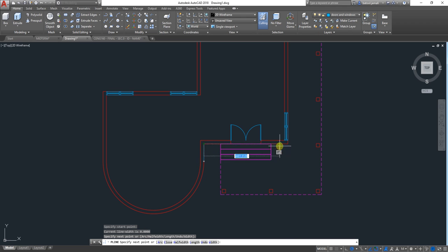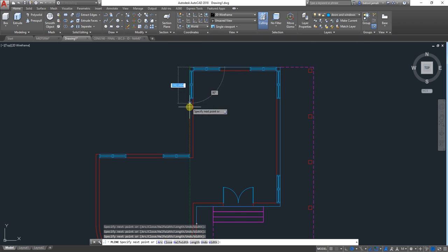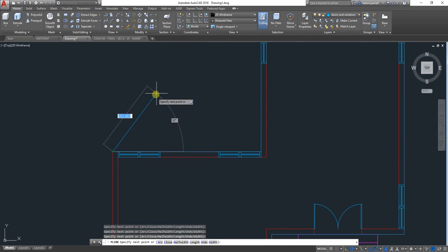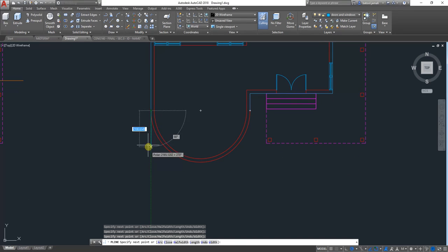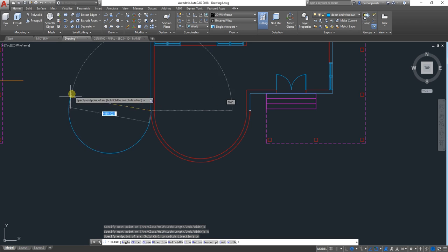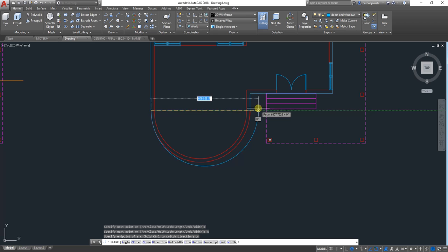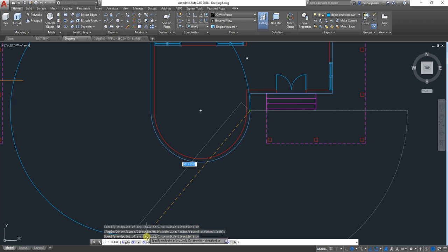Go around all the outer corners of your plan, just from outside. You don't need to go inside because we need only the borders. So this point, and then when we come to this part, we have an arch here. For this curve or this arch, you need to go down to the command panel and select arc here. When I select arc, it will give me this shape. Now we already have the first point, we just need to come to the second point, click, now we have it. Then you can select close.